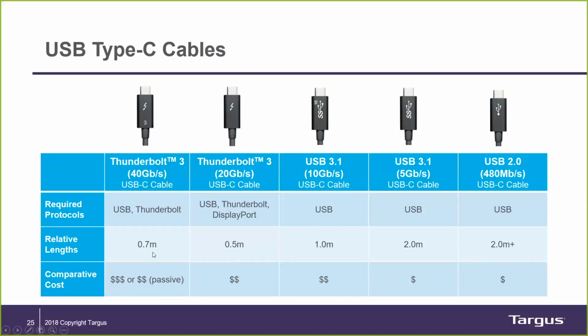That's kind of the leading edge, or the current edge, of technology. We are pushing to 1 meter right now. You will see on the Apple side a 0.8 meter Thunderbolt 40 gig cable. It is out there, but for the most part, the 0.7 is where they sit. And the lower speed cables out there, around 0.5 meters at 20 gig, are pretty safe.